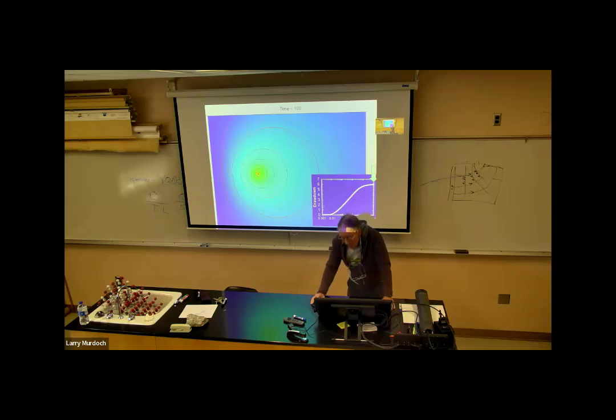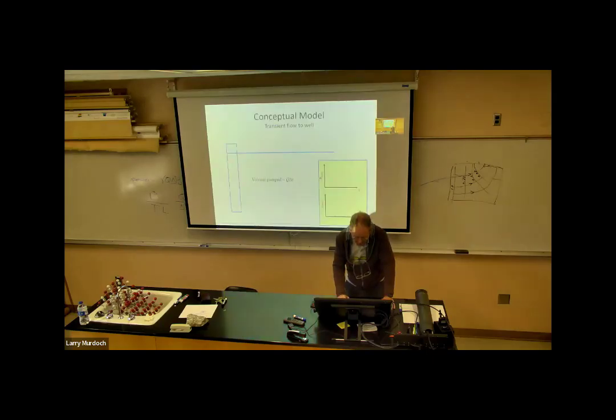Okay, so right in here, the well is progressing, we're pumping water out and the drawdown is increasing. That's not steady state because the drawdown is continuing to increase. But now here we've reached what looks like it could be steady state. We probably want to go a little bit longer and see if it really has flattened out. Okay, so there we have just the conceptual. Well, it's actually a model, so this is really numerically accurate, but this is showing some of the aspects that occur as you pump a well that's near a boundary.